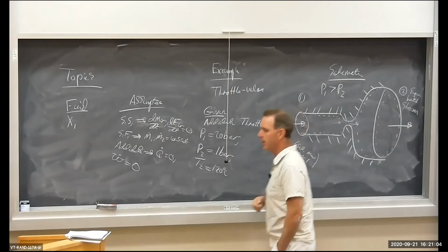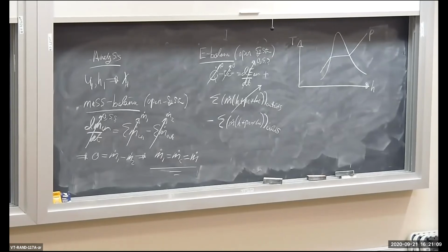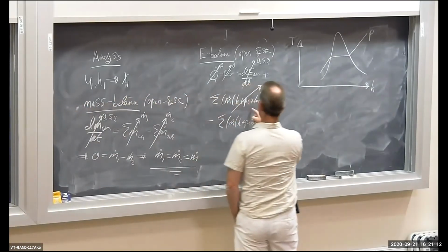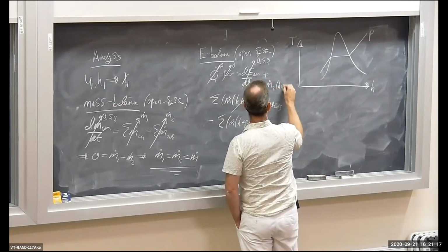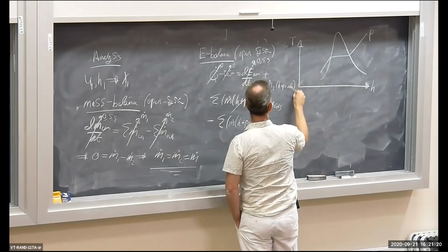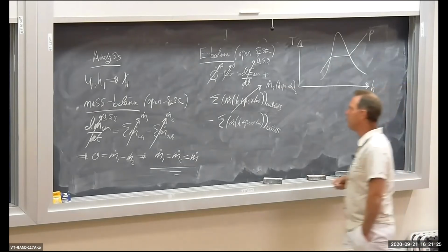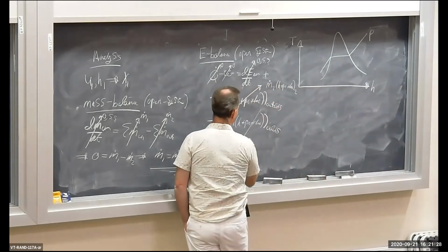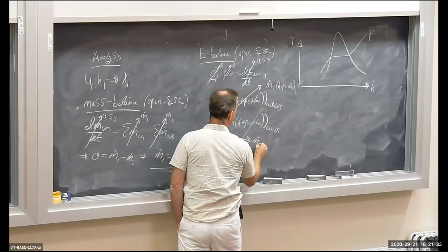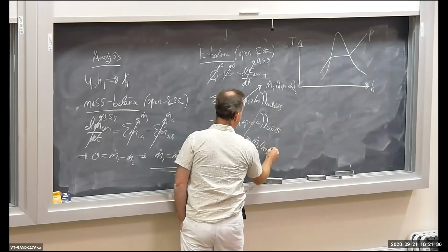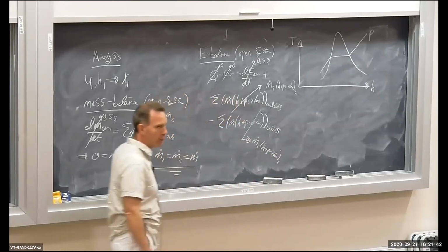We also have one inlet, at location 1. So the summations go away, and the outlet term becomes m dot 2 times h plus PE plus KE at location 2. At the inlet, the summation goes away, and I get m dot 1 times h plus PE plus KE at location 1.